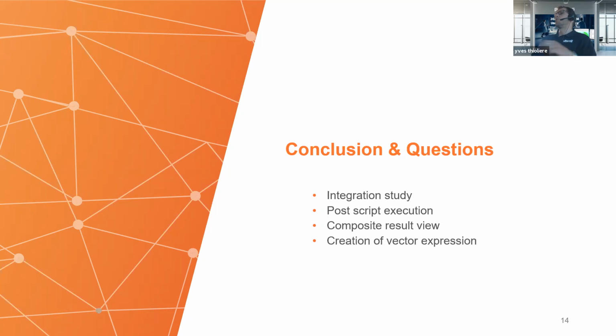It's not purely sinusoidal calculation anymore. You can have your PWM inside JMAG. And the efficiency map will be calculated using the last electrical cycles, when you reach steady state. Please check the tutorial on the JMAG website. So you can take PWM into account in the efficiency map for sure.